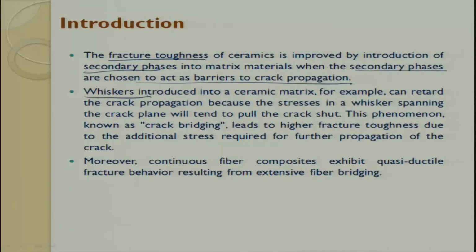The whisker and particulate, the difference is aspect ratio, is introduced into the ceramic matrix for retarding the crack propagation, because the stresses in the whisker spanning the crack plane will tend to pull the crack shut. This phenomenon is called crack bridging. Crack bridging is a very important phenomenon.